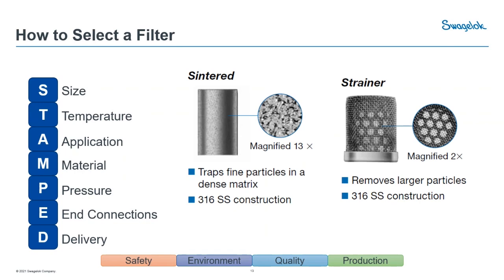And then as a general rule in selecting your micron as well, your filter size, to help prevent clogs in the system and help prevent the filter itself from clogging, the micron size should not be any larger than the smallest orifice of your system. So anything larger than that, if you're allowing a pore size that will allow larger particles to get through, you could end up with clogs in a small orifice in your system down the road. So make sure that you're keeping that in mind.